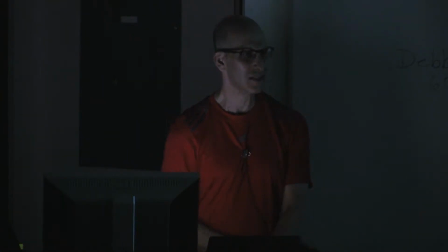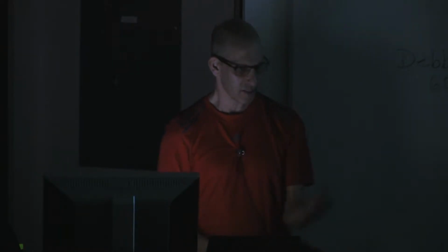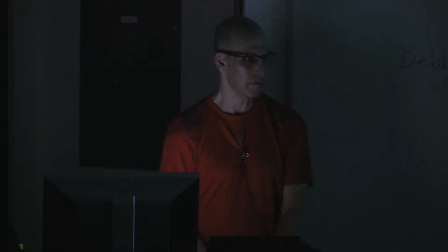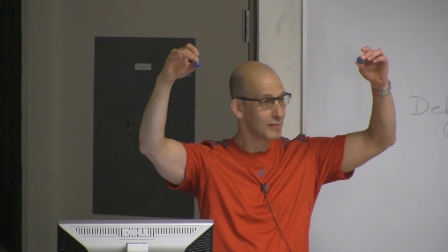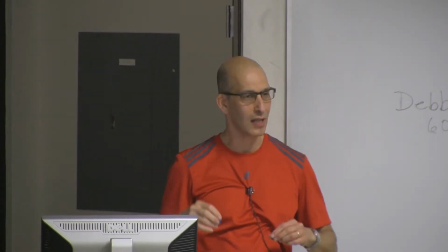And I stuck my hands in there and tried to fiddle around, pulled the fittings off and looked and all of that, and then stuck my hand into the fitting in the pump. And it was blocked, okay? This is why it was blocked. I don't know if you can all see that, but this is a little plug that was in that fitting. And then on the effluent end, the same thing was there. So it still didn't work, and there's the plug. So we had two plugs that we found that were in that line.